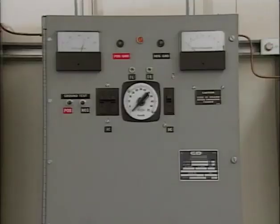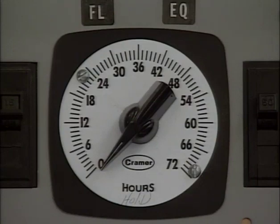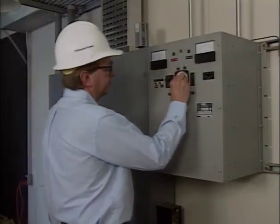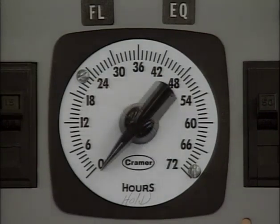A substation battery charger will also typically have a switch or timer that is known as a float equalize switch. The terms float and equalize refer to two different charge voltage levels that may be applied to the battery. When the timer is off or at zero, the charger operates at a normal preset float voltage. When the timer is activated, the charger operates at a predetermined higher equalize voltage for the number of hours for which the timer is set. After the time elapses, chargers with a timer automatically return to the float charge voltage. Chargers with a switch must be manually switched to the float charge mode.